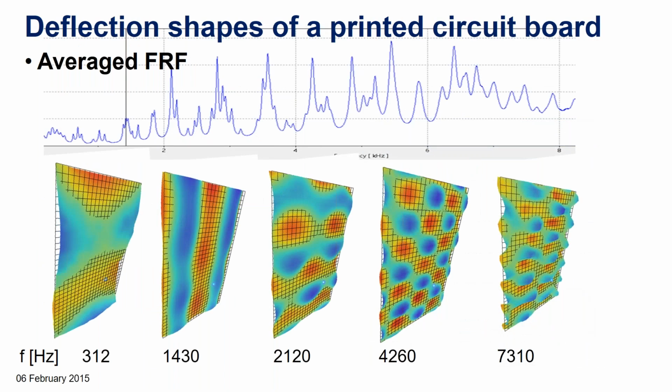And then what we did is we basically did a frequency sweep. So we swept from 0, in this case up to 10 kilohertz. Broadband excitation, we took measurements at every single point, and then we basically mapped that out. So each frequency in that spectrum, you can see the average FFT at the upper graph there. This shows you all the resonant frequencies going out to 10 kilohertz.